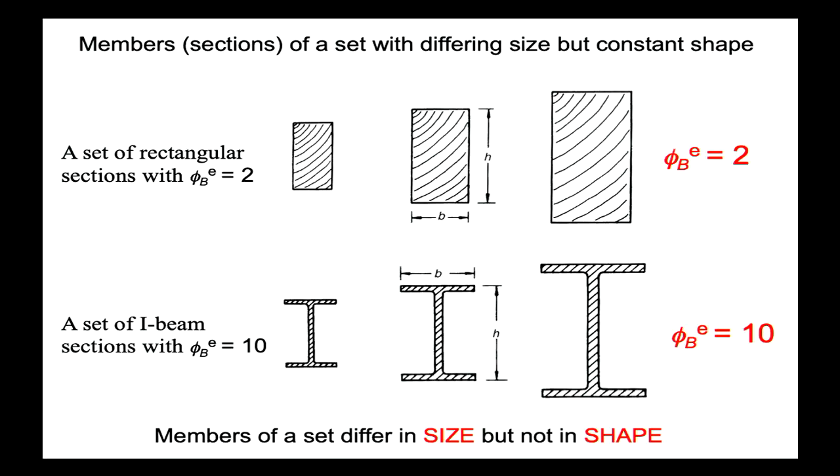Timber, hopefully everyone in the room can appreciate that until we start laminating timber, it has to be pretty proportional. We can't have it too thin or it loses any kind of material property. It'll just crack and pop due to the grain structure of it. Now, I'm not saying it limits or saturates at a ratio of base to height of about 2, but it's not going to be as high as 10, just as a tree trunk cut up.